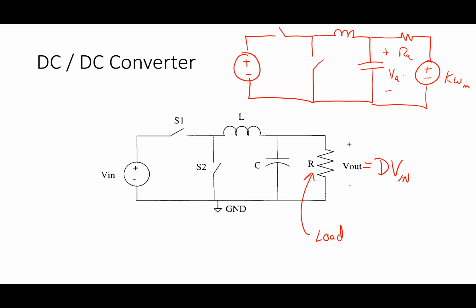Nowadays, they basically just take that voltage and straight away with a rectifier convert it to DC. So it's a big high voltage DC. And then they put it into this buck converter, which operates at a really high frequency, maybe 100 kilohertz or more. At 100 kilohertz, all of my components can get a lot tinier, and now they can fit into that little cube, right? As opposed to that big fat thing. So power electronics are really important.